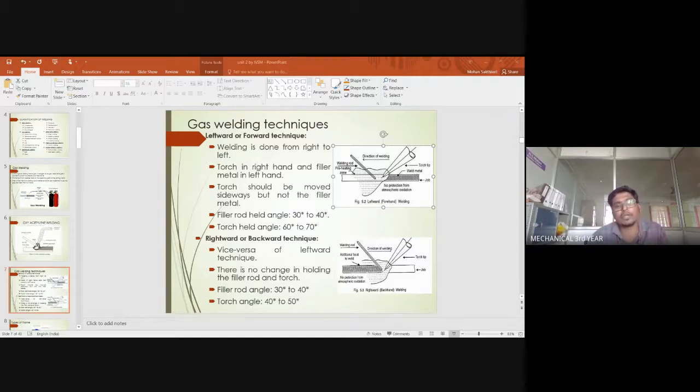Okay, so here we have the typical diagram of the arc welding process. Let us discuss what parts are available in this particular diagram. You have metal droplets, which means the metal is getting converted into liquid form and is being deposited over the base metal. And we have an electrode coating. Here you can see a slight mesh-like appearance. This is your base metal, which is completely white in color, whereas here you can see some hatches. These hatches represent the coating.